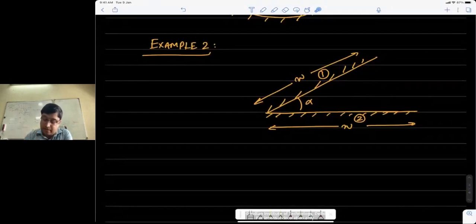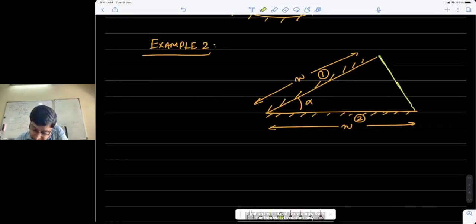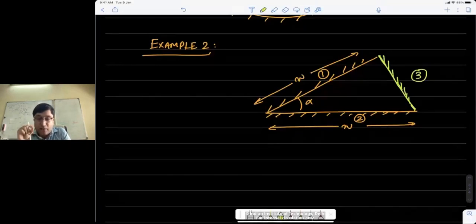So what I can do, and probably some might have figured it out, is draw a fictitious surface here which sort of closes this problem. So I draw a surface 3 which says that whatever radiation goes onto this surface 3 is actually what is escaping into the room, or into the surroundings, if you want to say it. So let me say this is surface 3. Now the problem becomes slightly easier, because now I know that inside this enclosure radiation will be conserved.